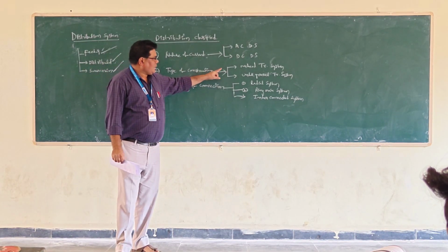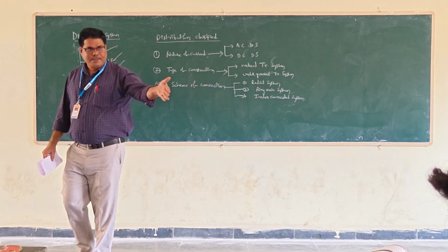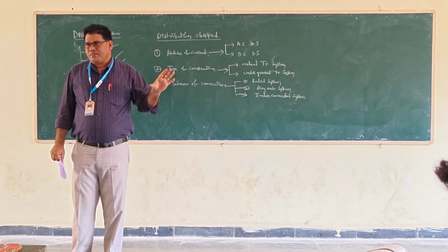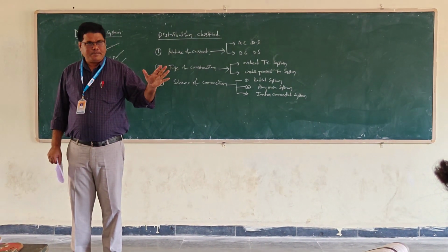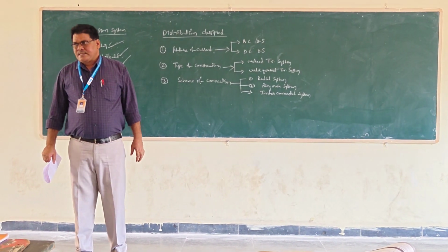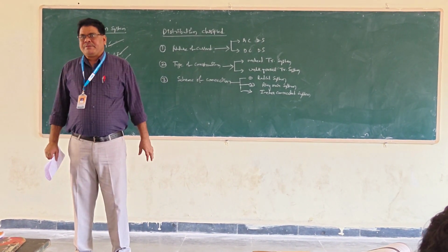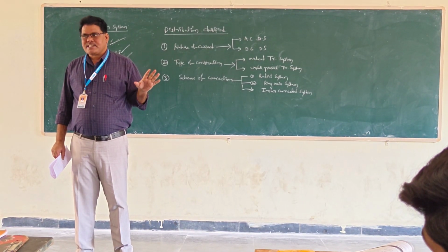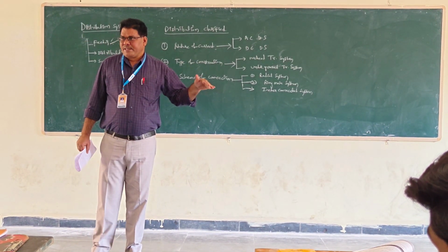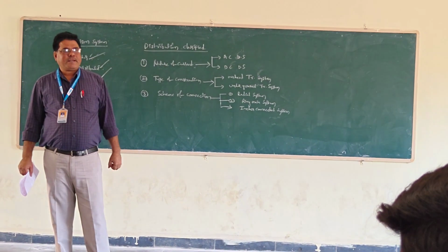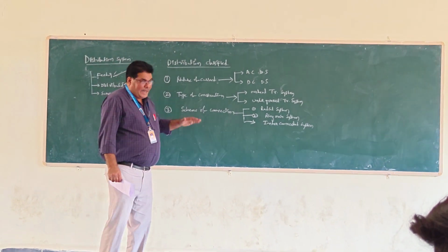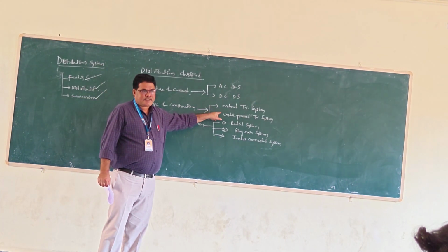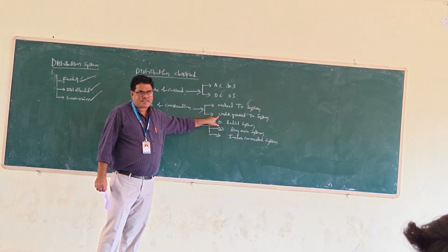Coming to overhead transmission system and underground system. Already known: the underground system uses cable. Cable means insulation failure is a difficulty; at some voltage the insulation is better. So due to the difficulty of insulation failure, underground cable is limited to 66 kV. But our voltages are very high: 400 kV, 765 kV, 220 kV. So higher voltage requirement is needed, so that we use the overhead system more. Underground is limited to 66 kV.